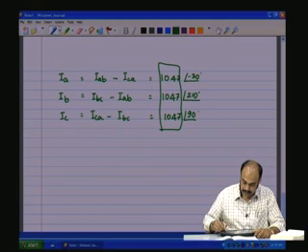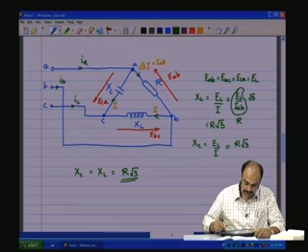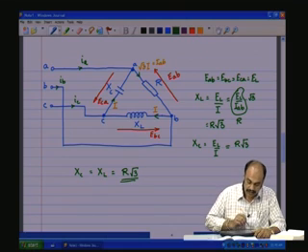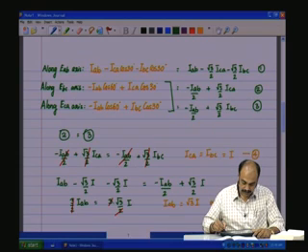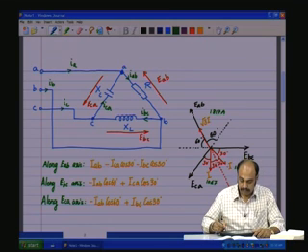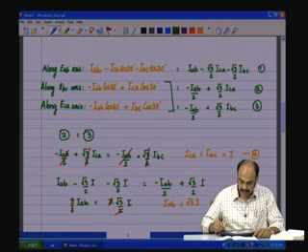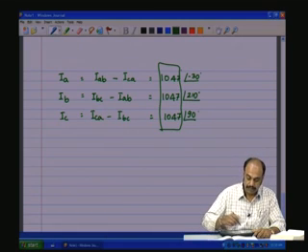However, in the case of the phase currents, we have this artificially included I and root 3 I, but effectively they all will cancel out if you put it along the 3 axes as we show, using these equations, which effectively cancels out on all the other axes, and you will have only the IAB component flowing through, which is the effective power. But from the line side, from the source side, it will look as though they are balanced.